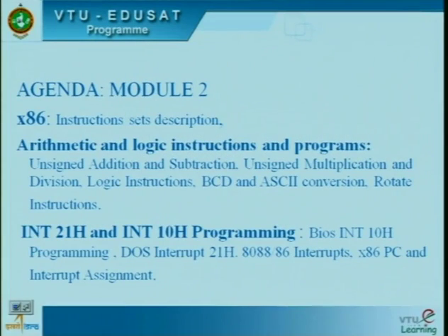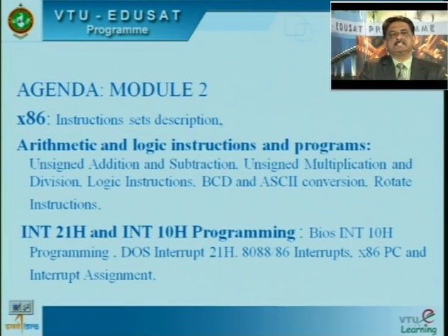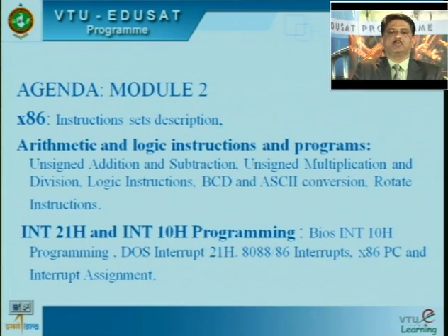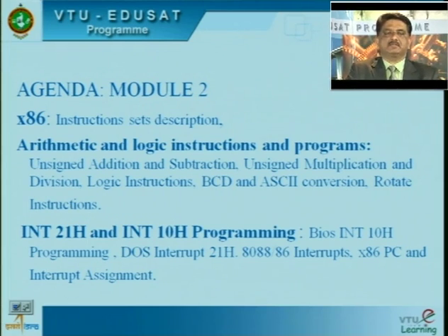Today, we shall discuss the instruction set of 8086. The agenda for the day, as per the VTU syllabus, is module 2, where we will be discussing the instructions and their descriptions. Particularly, we will concentrate on arithmetic and logical instructions and programs related to them, and we will end this module with a discussion on interrupt number 21H, interrupt number 10H and related programming.